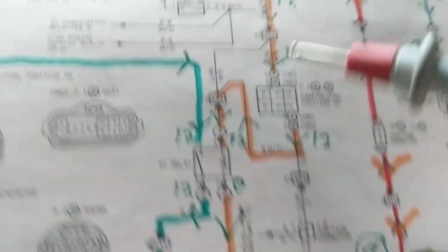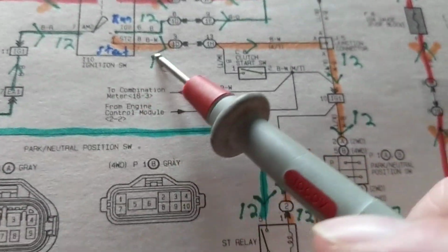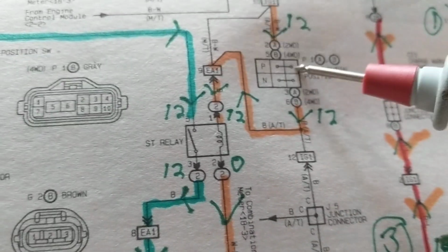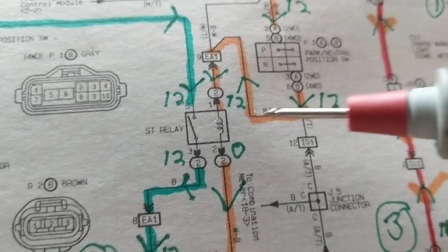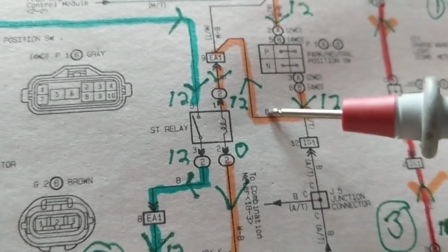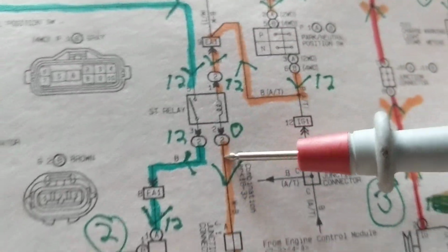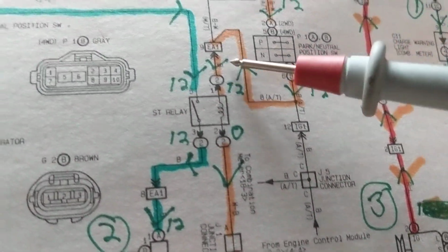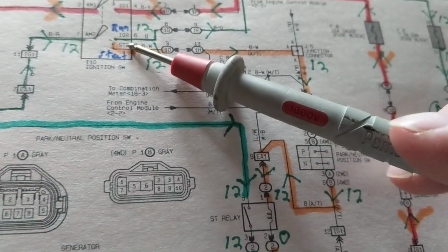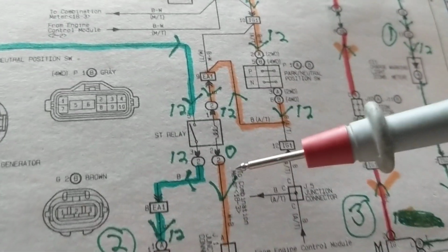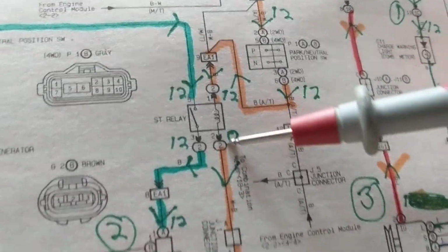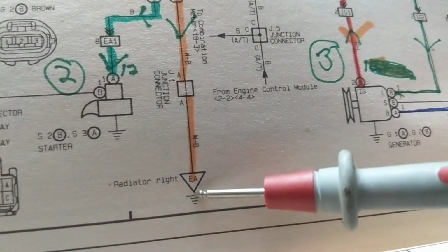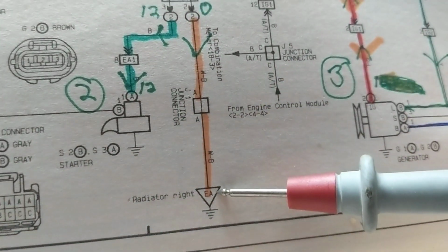How do we activate this? We activated this through the start of the ignition switch. And then we made sure that we were in park and neutral, not in reverse, not any other selection. So we go here, and we go right to ground. Follow this thick orange. We have 12 volts where? From here and here. We said before, we can even get a ground from where? The computer or a physical ground. Is this a physical ground? That's the radiator, right. This is a physical ground.